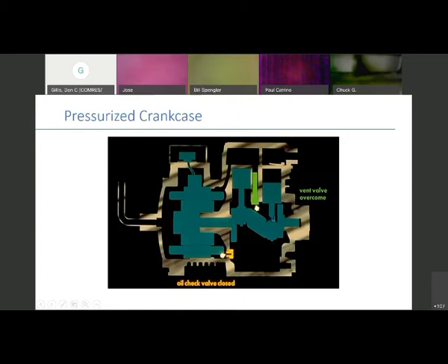This part of the crankcase pressure increases, then it depressurizes. This opens up, the oil goes back to normal, and fills that sight glass halfway up where we like it. Then the technician comes out to look at the compressor and is scratching his head because the oil's back in there, but it was tripped off on low oil.